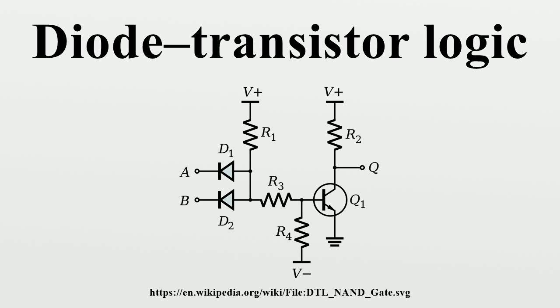It had a compact layout, it had no minority carrier charge storage, and it was faster than a conventional junction diode. His patent also showed how the Schottky transistor could be used in DTL circuits and improve the switching speed of other saturated logic designs, such as Schottky TTL, at a low cost.